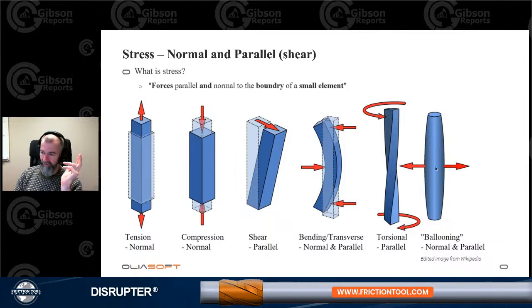You'll just fill it at certain intervals. Say you run it 1,000 feet or 2,000 feet, and then you fill it up to the top side, and then you run another 2,000 feet of pipe. Of course, in those cases, you will have pieces of pipe that are submerged in mud but where there is actually air on the inside, and then you get into these scenarios where the walls here will actually be compressed.